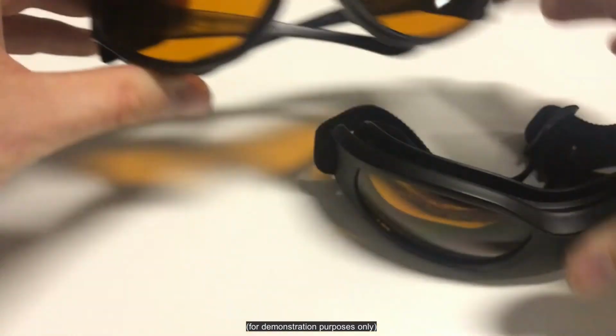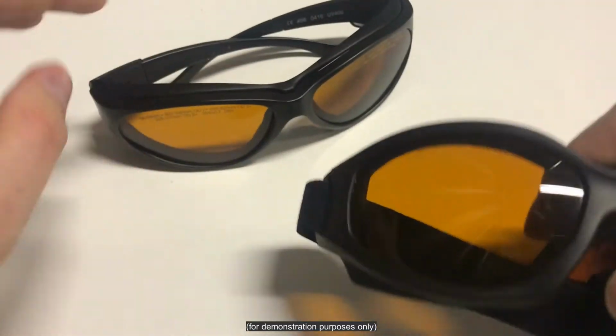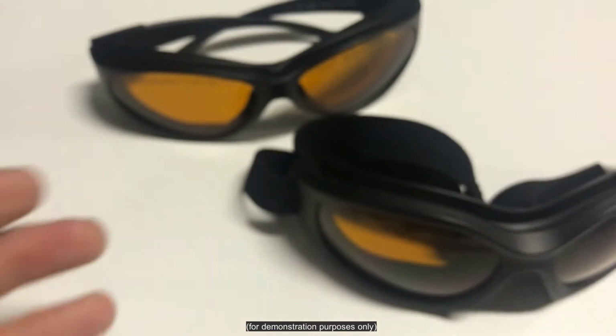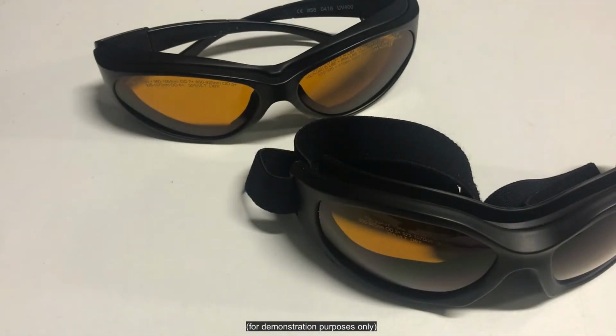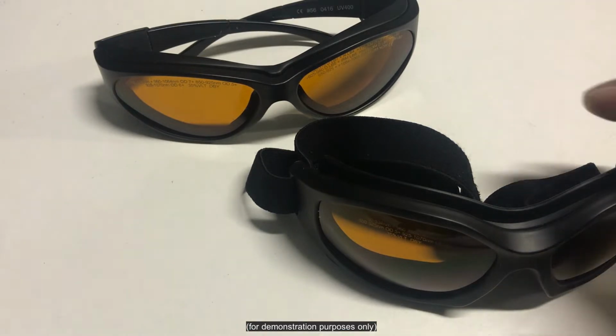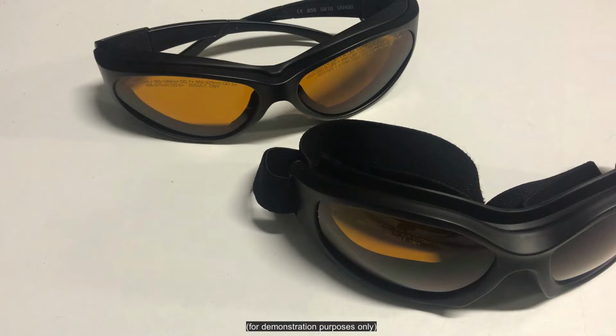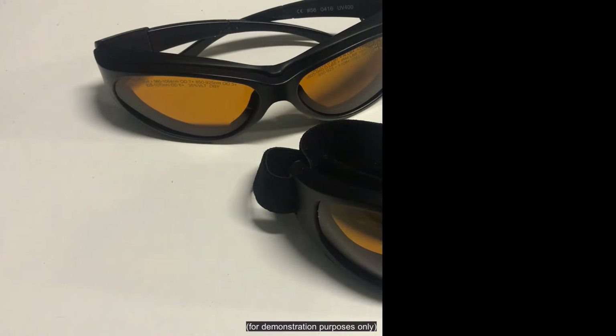These are the ones I'm going to be wearing, and I'll be holding this occasionally in front of the camera lens. If you just look through, obviously it turns the whole world orange, but what's quite good about these is they're sometimes called alignment goggles. You can actually see a very small amount of the laser light is allowed through, and that's quite handy with the task we're going to do next, which is aligning the laser plane to our plane of interest, the plane where we want to take the measurements.